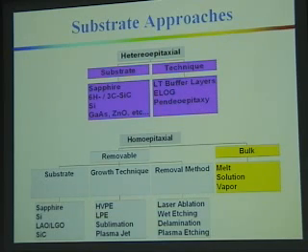What I'm going to talk about today is this side here. To do homoepitaxy on gallium nitride, but to grow gallium nitride very thick onto a removable substrate. So we're just going to take a substrate that's well lattice matched, use it for a template, grow very thick gallium nitride, 200 microns or so, and then remove the substrate to produce and leave behind freestanding gallium nitride.